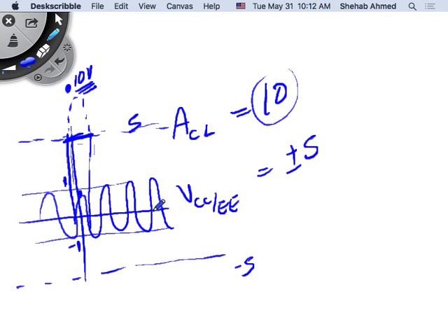So you distorted the signal because you tried to operate outside your supply voltage rails. And that's why, remember all of the discussion about offset voltage and bias current. The problem with the circuits without taking care of these issues was that the offset voltage and bias current were passing through my circuits and being amplified. What does that mean? They're eating from my ability to produce a larger useful signal at the output, right?